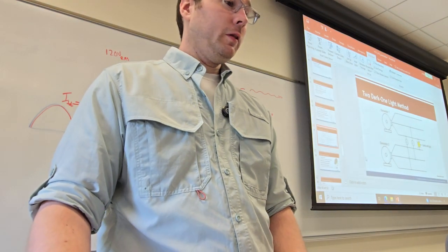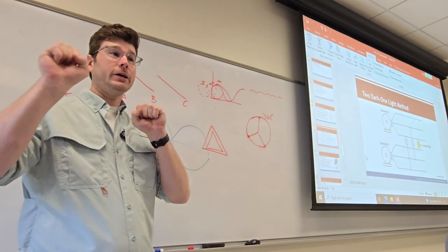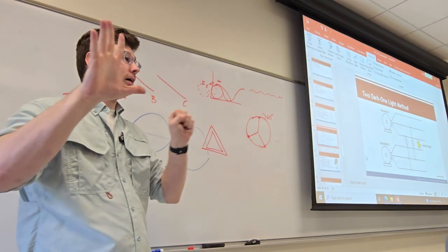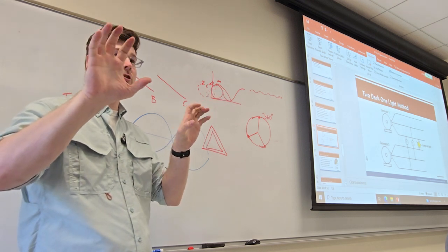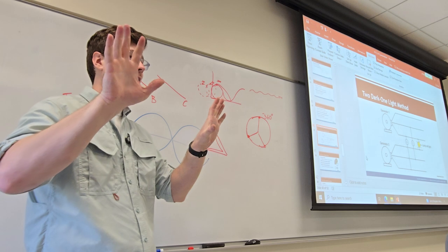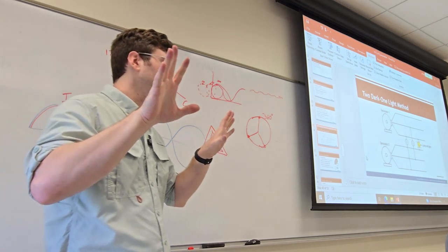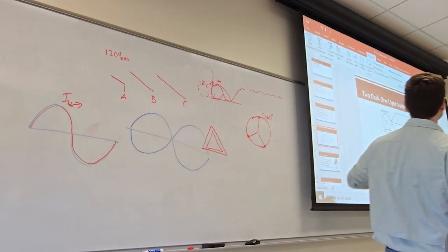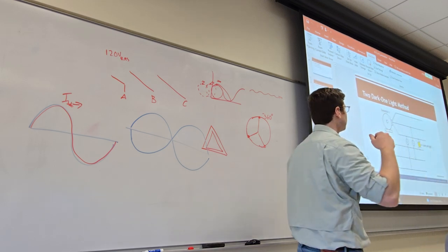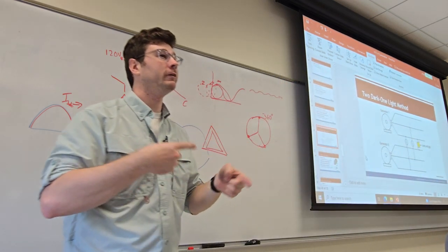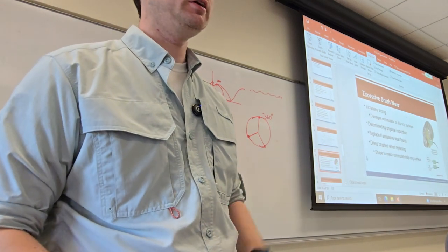All right, well, I'll maybe look back and see if I can find it, but essentially, there's 2 lamps that will slowly flash. The right one will flash, then the left one will flash, and then they kind of sync up, where one will slowly flash until they're both lit for some amount of time. It's like 2 sounds that are syncing up, and then you'll kind of hear them wub together. That's just like what they do here. They see that these 2 lamps will come on in phase, and then they throw the switch, turn on the generator, and then the 2 generators are perfectly in phase, according to that indicator. And they won't destructively interfere, they will constructively interfere.